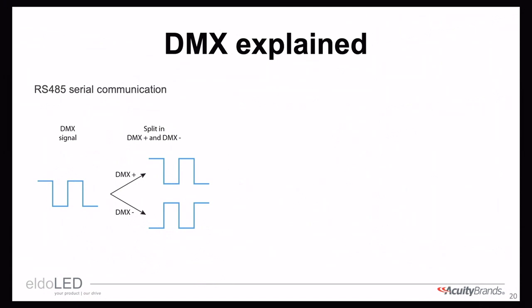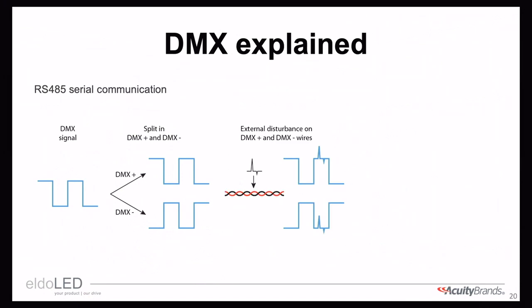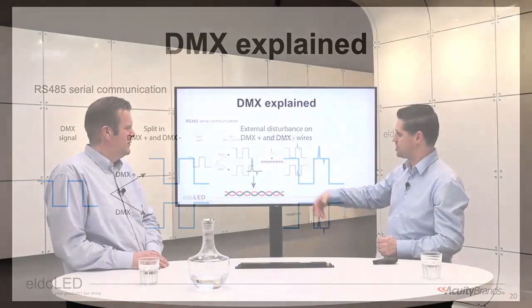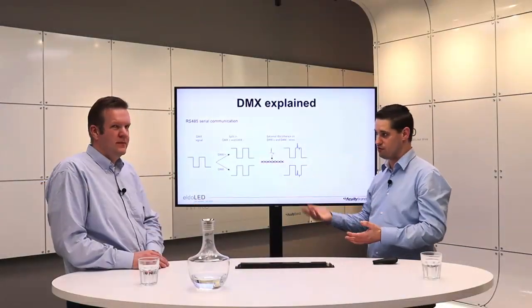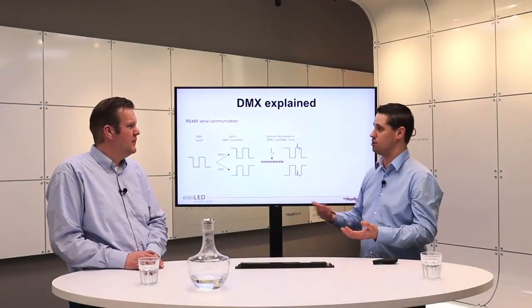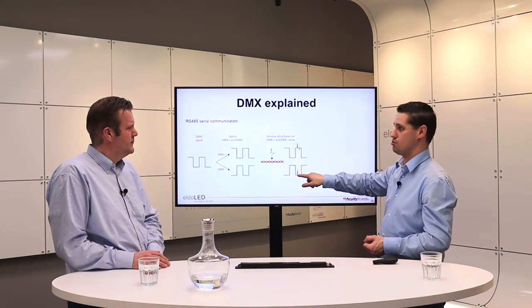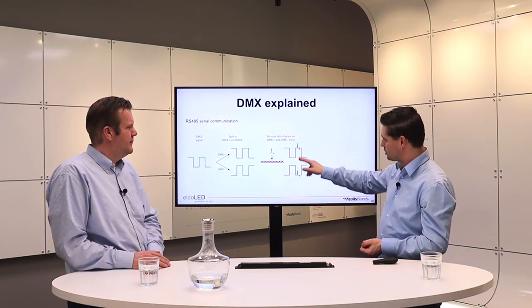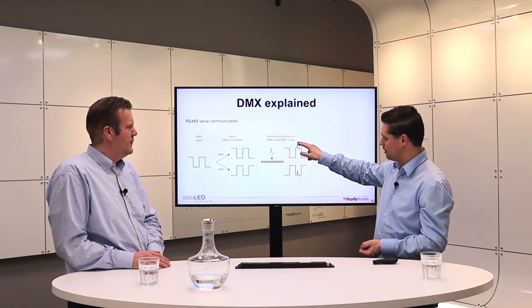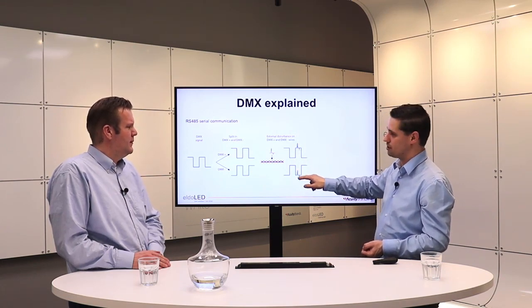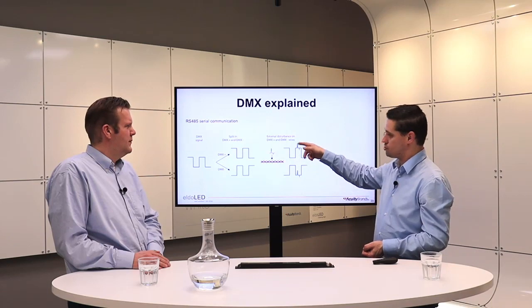Because those are the opposites of each other, if we then apply a signal disturbance on the cable, that same disturbance or interference or whatever spike you get from a noise perspective on your cabling is affecting both signals the same way. It's lifting the pulse a little bit higher and also the low end a little bit higher. You get the same peak on the same 2 channels.